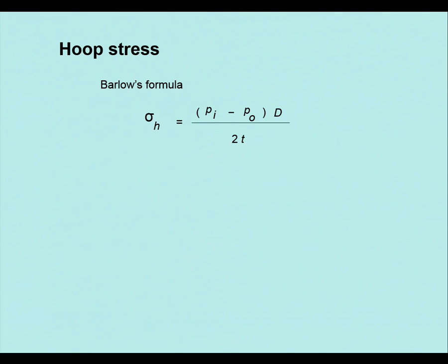I would just assume you are absolutely right as usual, and I would just stick with the outside diameter. Okay. But some codes don't stick with the outside diameter. Sometimes they use a nominal diameter. And we said yesterday that a 6-inch pipe can have an outside diameter of 6.625, but then they'll use the nominal diameter.